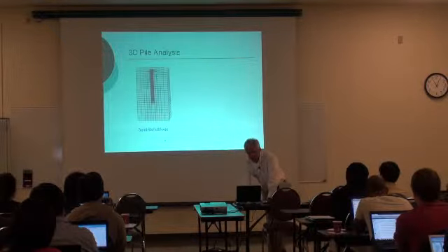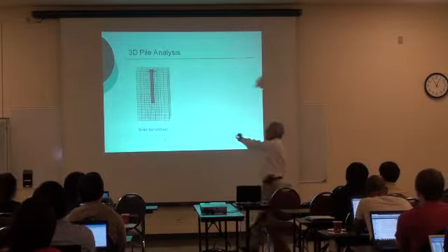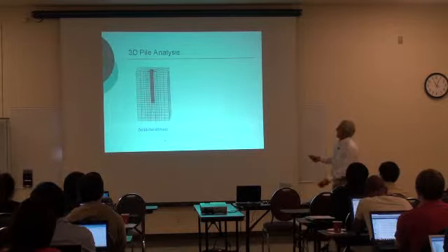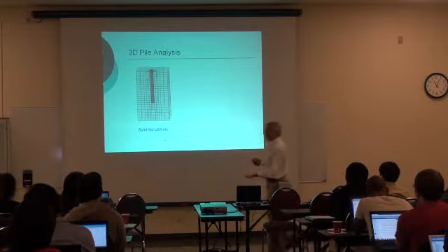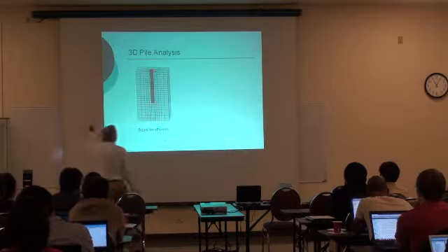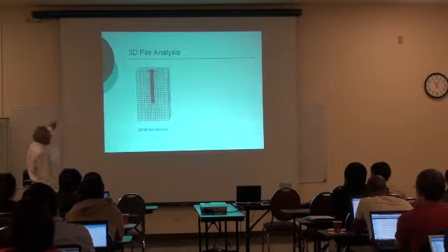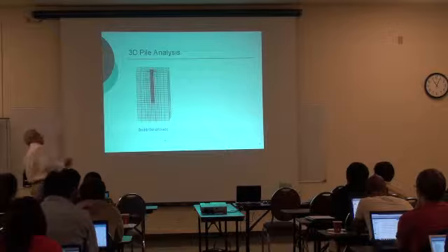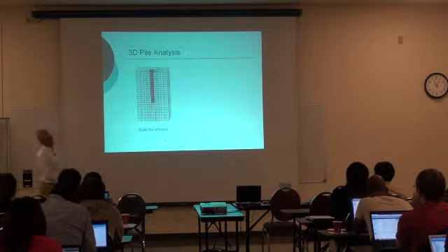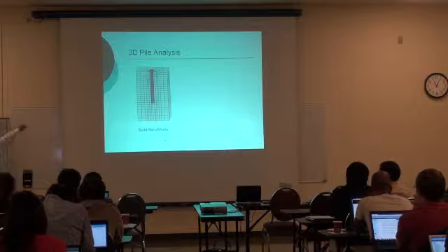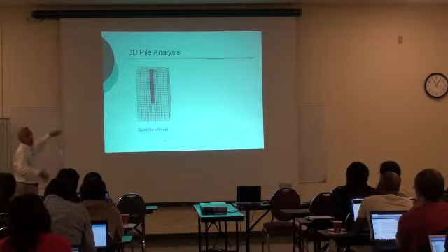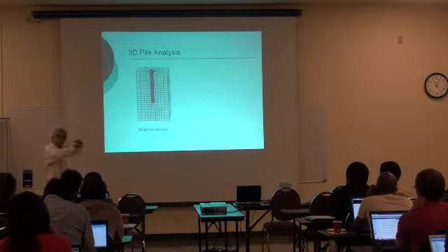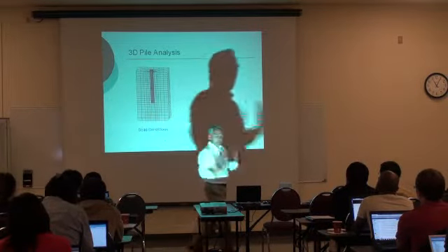Finally, 3D analysis of piles. Again, we can model the pile using solid elements, and the soil using solid elements. Now, what's the problem with this? The problem is that usually what you are interested in is the demand in the pile in terms of shear forces and bending moments. How to get the bending moment from solid elements? If you go to your mechanics of materials, you can say, I can calculate my stresses, integrate my stresses, and calculate the equivalent bending moments at each level. I could do that, but it's problematic.